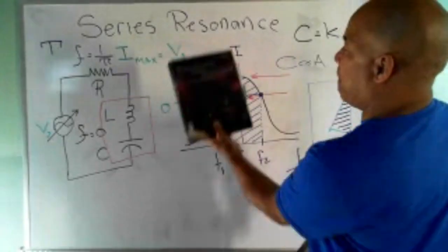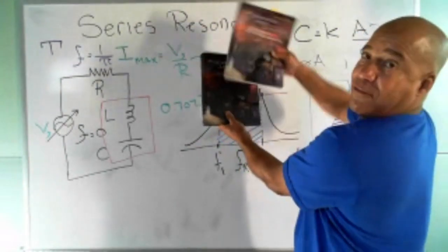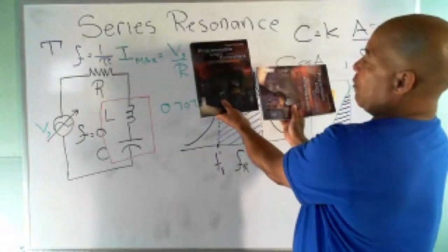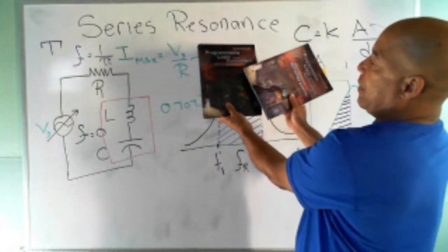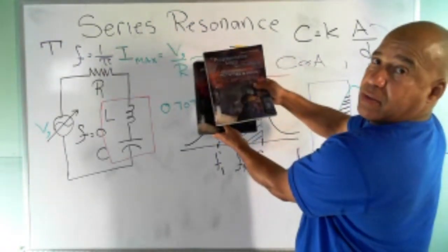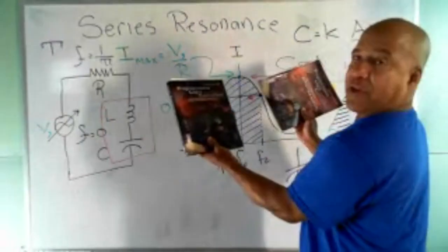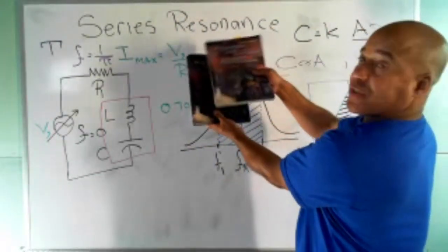So imagine now I have a fixed piece of metal, and I have another one on a hinge that I can move back and forth like this. I can have it over here, and I can turn the knob, and I have more and more mutual area until I have the whole area, if you follow what I'm doing. That's a variable capacitor. I just designed for you in front of your eyes a variable capacitor.